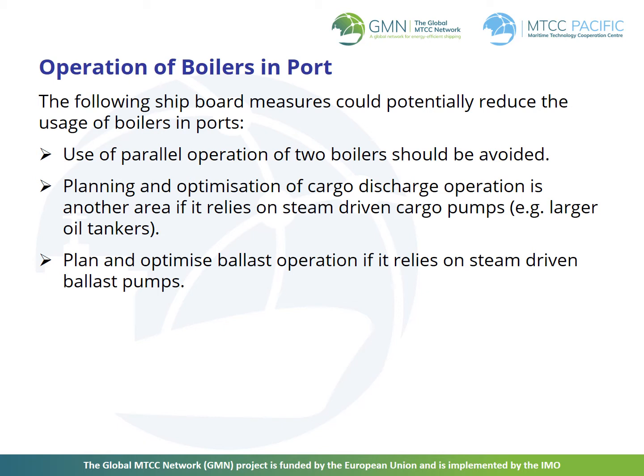Planning and optimization of cargo discharge operation is another area if it relies on steam-driven cargo pumps, for example in larger oil tankers. In some of the ships, there may be provisions for a mix of electric and steam-driven pumps. Proper planning could be done to avoid excessive use of boilers. Plan and optimize ballast operation if it relies on steam-driven ballast pumps.